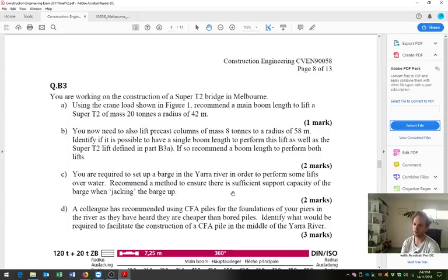I mean, you could do a cofferdam, but I think you probably should have a barge in this instance, because you're going to have to cofferdam off so much of the river to put in a pile. A barge is definitely the correct answer here. We did focus a lot more on waterway crossings this year as well, so it's probably less pertinent for 2018.